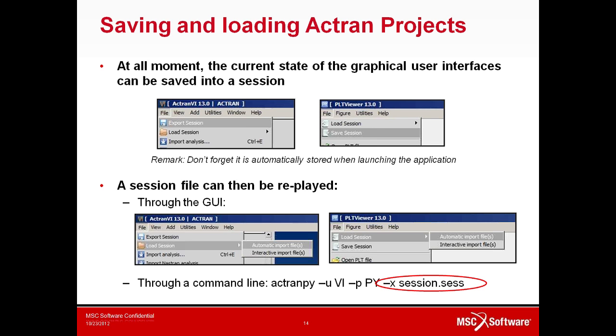When loading directly the Graphical User Interface, the user can either choose to import the previously imported files, supporting the mesh or result files, or to interactively import these files. It is already a good example of how to use templates actually. When using the batch mode, the user can choose to work in non-graphical mode, allowing to perform pre- and post-processing operations directly on a cluster, for instance.